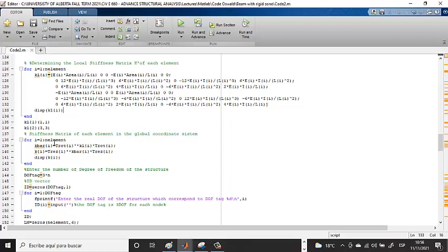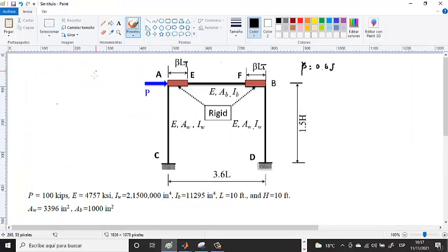And after that, we will calculate the stiffness matrix in the global coordinate system. We are doing this in order to assemble the global stiffness matrix. So maybe it's important to notice what K bar means and what K alone means, using the rotational transformation matrix and the rigid end zone transformation matrix that we defined previously. So let me explain here.